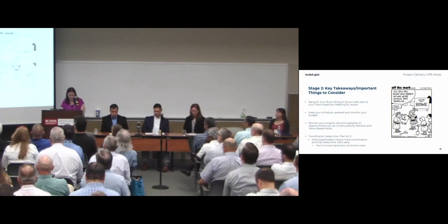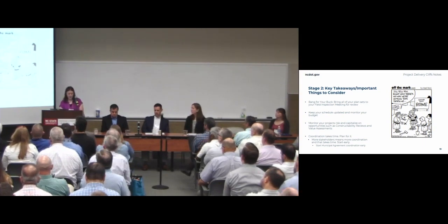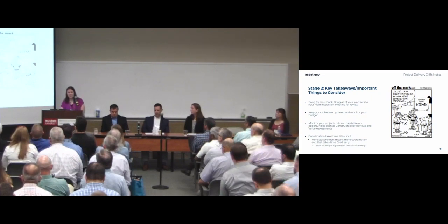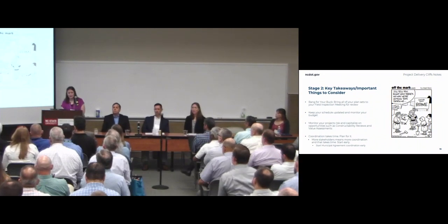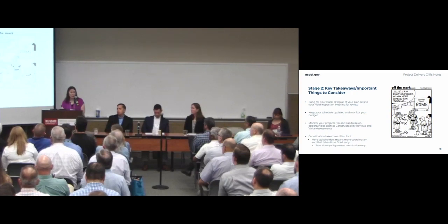I've also had several occasions in field inspections where traffic management plans flushed out design flaws. Again, is it buildable? We reviewed utility plans that didn't have sufficient easements or appropriate separation. Without these plans at the field inspection meetings, a lot of these issues will not come up or get addressed until the project gets let, and those things can be costly and time-consuming.